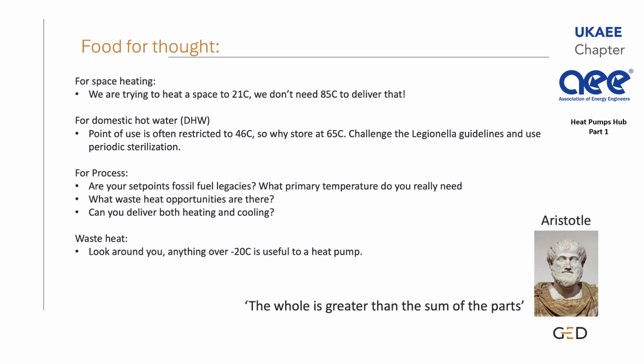Before I finish here, a bit of food for thought. For space heating, we're trying to heat a space to 21 degrees centigrade. We don't need 85 degrees C to deliver that. It's inefficient. For domestic hot water, point of use is often restricted to 46 degrees centigrade. So why store it at 65 degrees centigrade? Challenge the Legionella guidelines and use periodic sterilization.